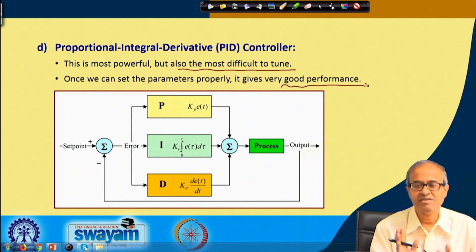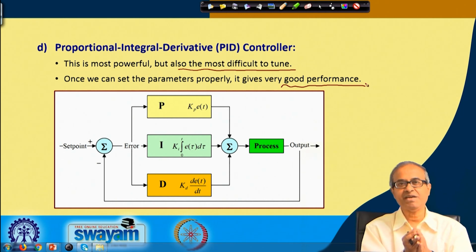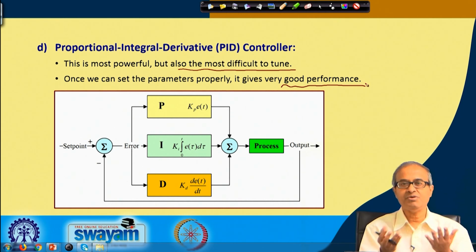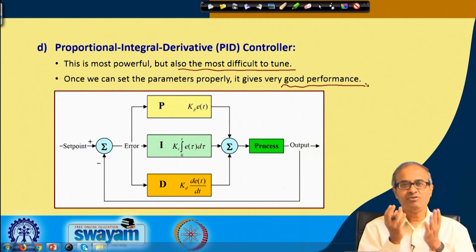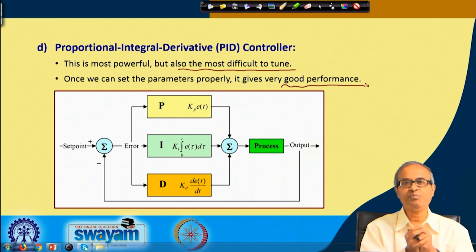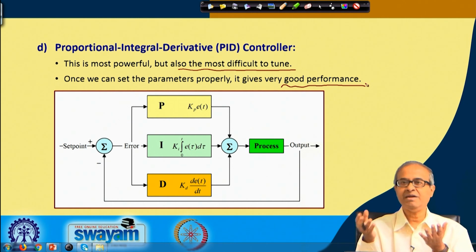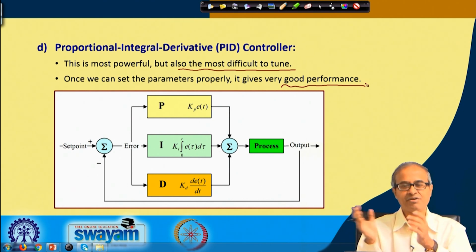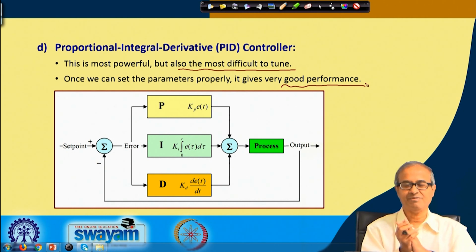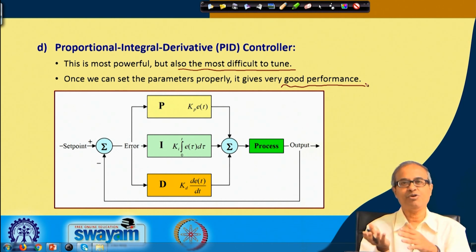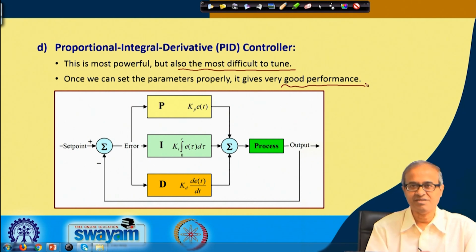So, PID controller is good in this sense, and in embedded system applications, because you are talking about controlling some appliances and all of these are feedback control systems, you may choose to select the appropriate mode of control. For some appliances like the refrigerator, this on off control is good enough, because you might have heard your refrigerator making a sound in the night, it is suddenly turning on, makes sound, suddenly turning off, those are on off control. But you can have PD control or PID control also in some more sophisticated application where errors in the output cannot be tolerated beyond a certain limit.